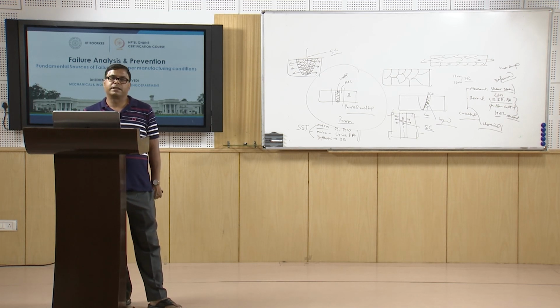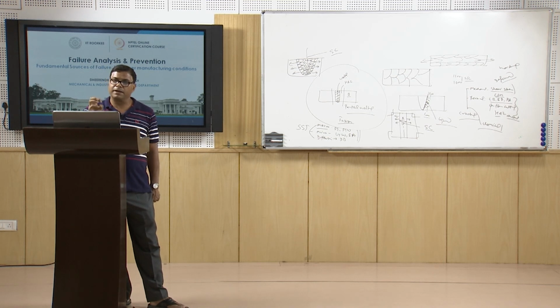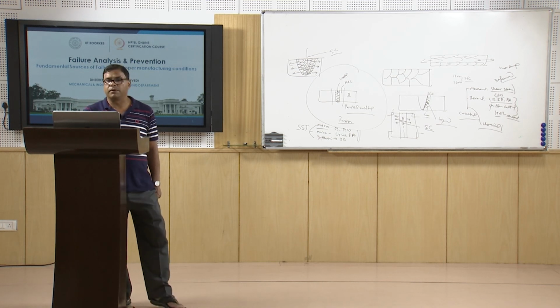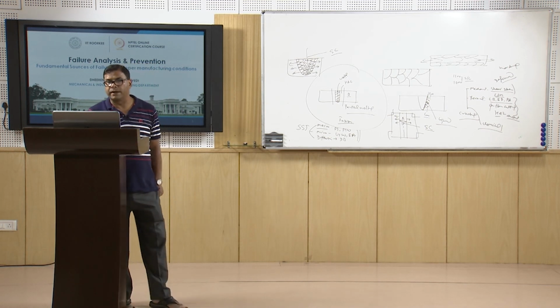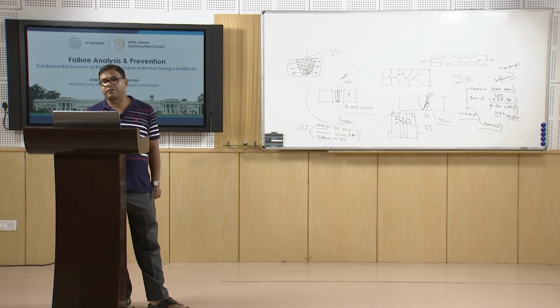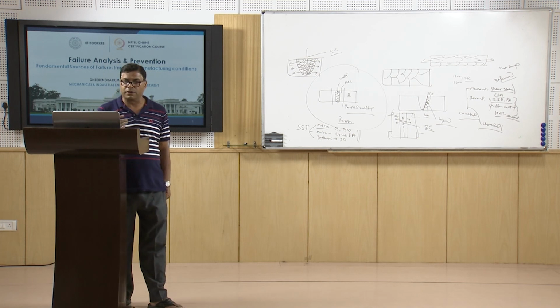Now we will see that hot forming or hot working does not cause much of a problem related with cracking or with anisotropy, but the products produced by hot working gain their strength from the controlled grain refinement. But apart from that, since the component is to be heated to a high temperature for hot working, that is above the recrystallization temperature of the metal, if the metal is heated to the high temperature, then it will have a tendency for oxidation.